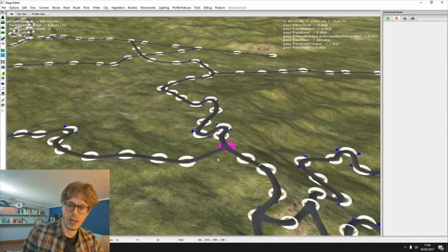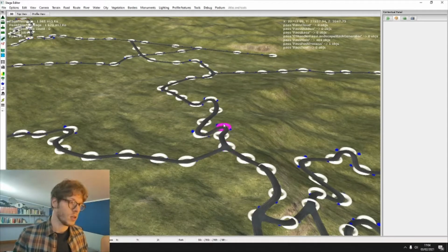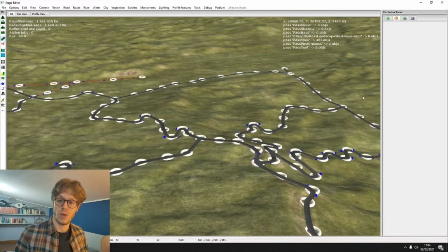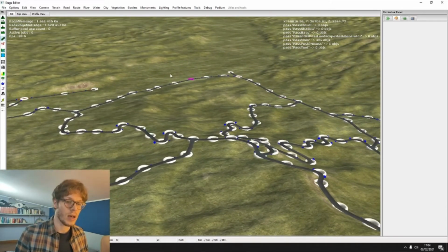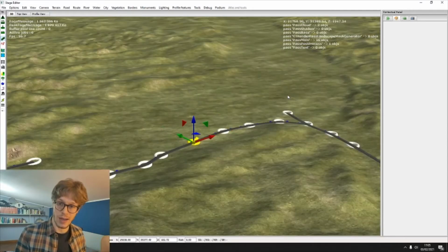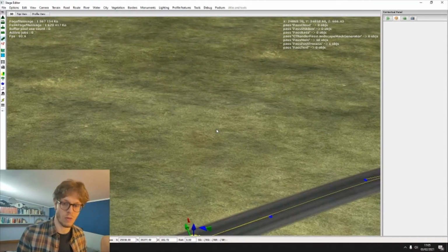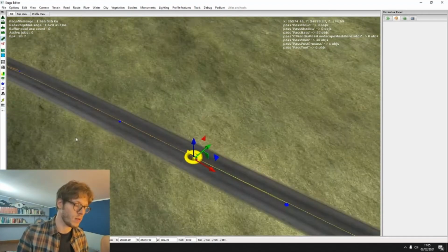I give you one other tip. There are a lot of fast keys on the keyboard for the stage editor. If I want to zoom on a point, that is an object, a point of the road, I must select one point, and then with the space bar, I click, and the monitor is focused on the point that we selected. Then, like I taught you last time, I zoom out and I zoom in.